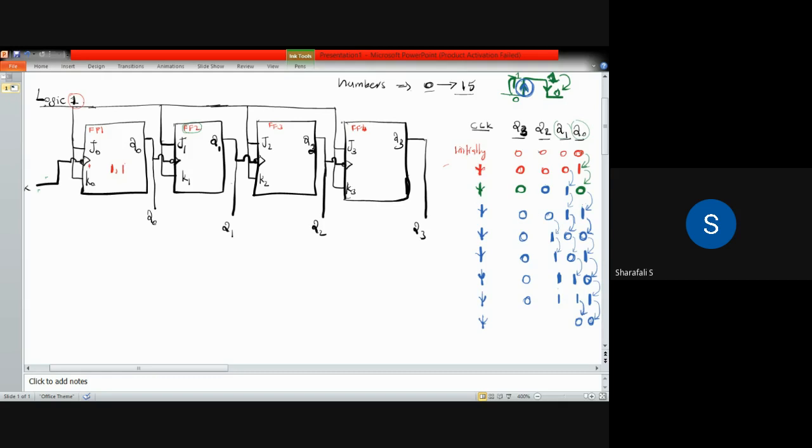So this Q1 is given to the third flip flop. This Q1 is at the negative edge, so the third flip flop, having a clock pulse equal to 1, will trigger and toggle the state. So 1 will change to 0. Since this is going from 1 to 0 for Q2, it is now in the negative edge. Q2 is in the negative edge, and that triggers the fourth flip flop, and it will toggle the state Q3, and that will become 1.